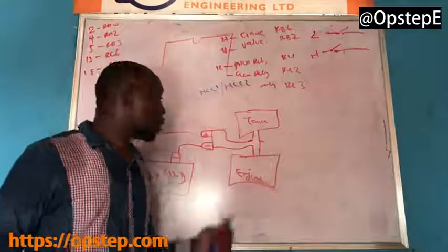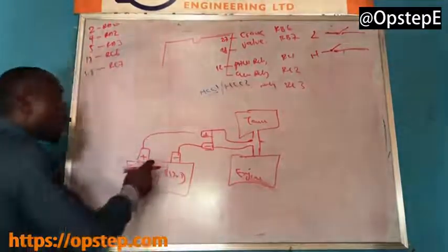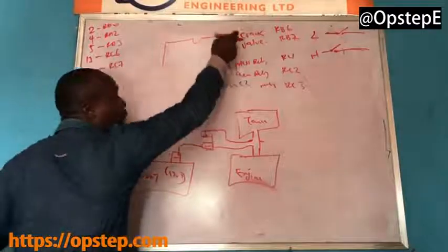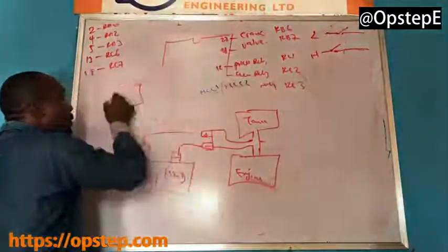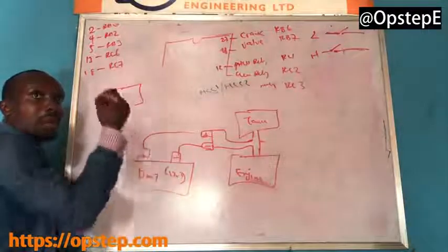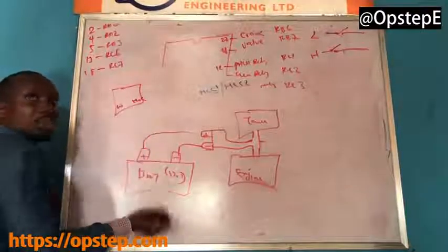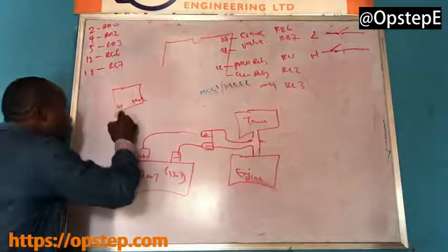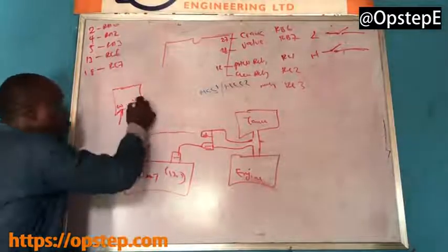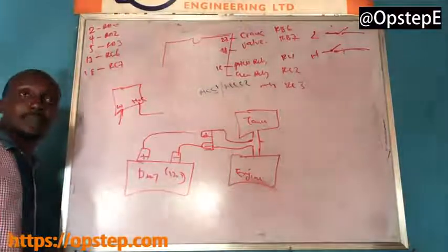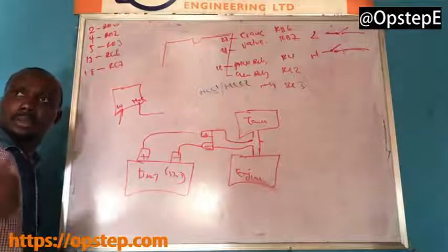Are you following me now? Yeah. So that is why, if you look at it, for your valve you are going to need a relay. Wiper, normally open contact, is the two things you need. What are you putting there? Put battery voltage here. Put this one on the other side. As simple as that. Do you understand what I just did?